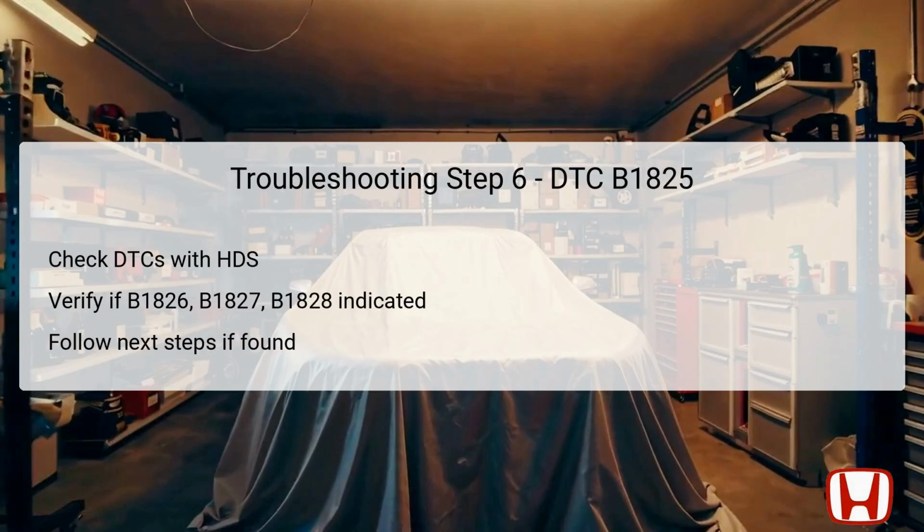During this step, you will again use the Honda Diagnostic System, HDS, to check for additional DTCs, specifically looking for B1826, B1827, and/or B1828. The presence of any of these codes in conjunction with B1825 suggests a more complex issue involving multiple elements of the power seat adjustment system.